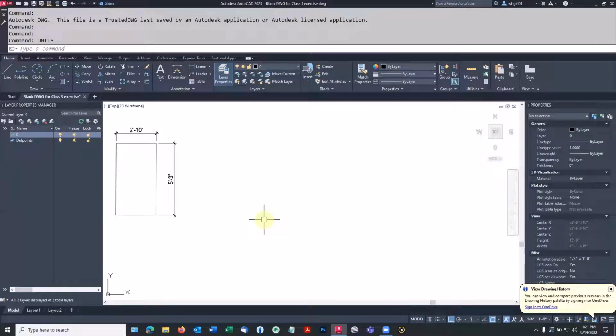And all these CAD programs are trying to keep their file sizes as small as they can. So if you have 300 room names in a hotel, it makes much more sense to use single line text, which might take 20 bytes per piece of text compared to multi-line text, which might be a kilobyte. So we have 2 different tools.